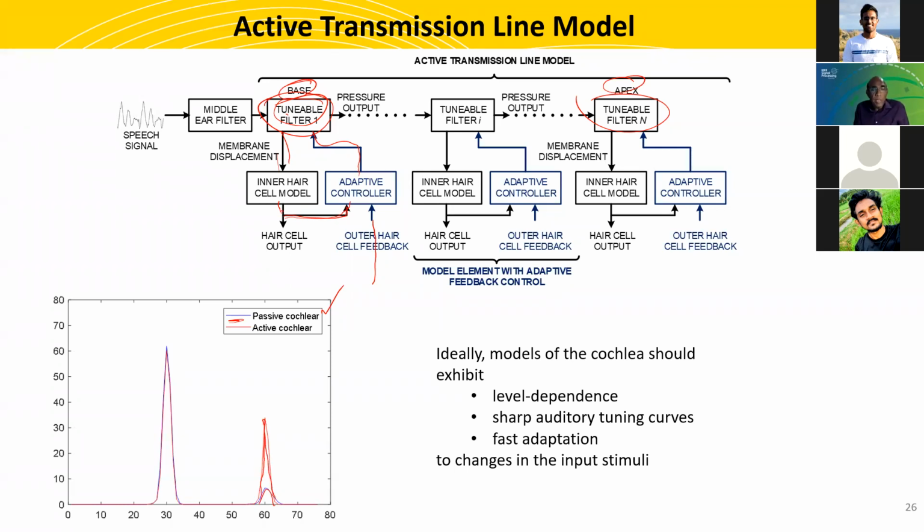Very important in speech applications, in spoofing applications, where somebody is trying to mimic you by recording your voice. So we need to extract the high frequency information, but it has very low amplitude. Very hard to get with the normal filter bank. So you need an adaptive filter bank that can actually pick it up, and I'll show you in a second.